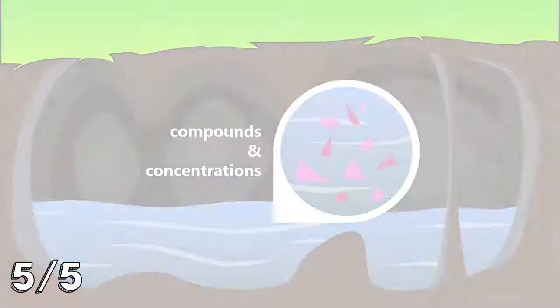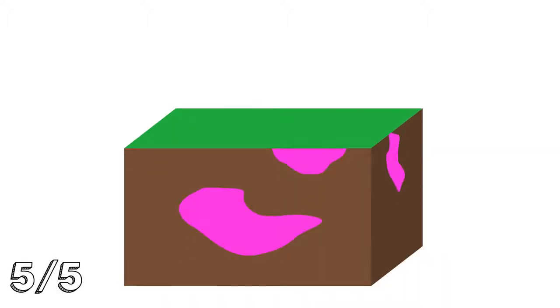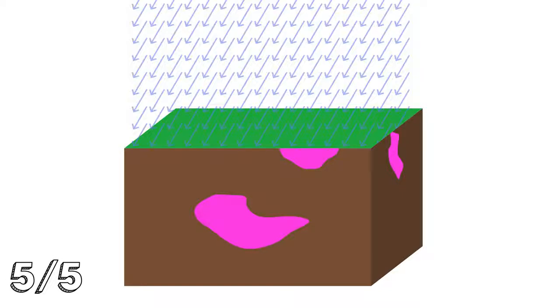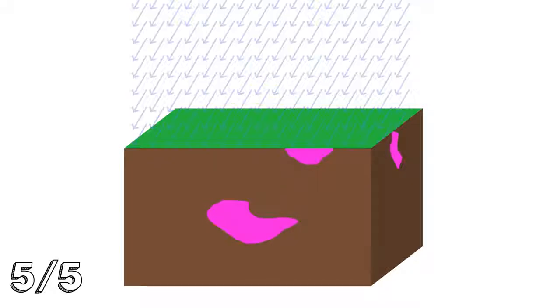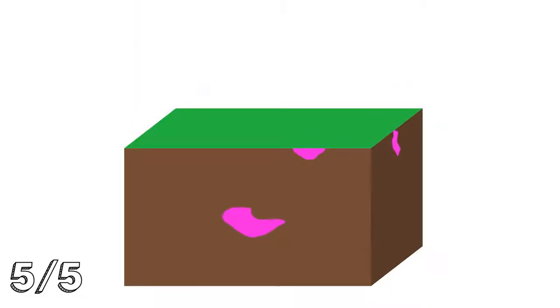An example might be a situation where natural attenuation has been selected as the appropriate strategy for dealing with a groundwater plume with a low concentration of contaminants where there is little potential for off-site migration. Relatively clean rainwater infiltration down to the groundwater may have the effect of speeding up the natural attenuation process. You'll need to discuss this with an environmental consultant before proceeding.